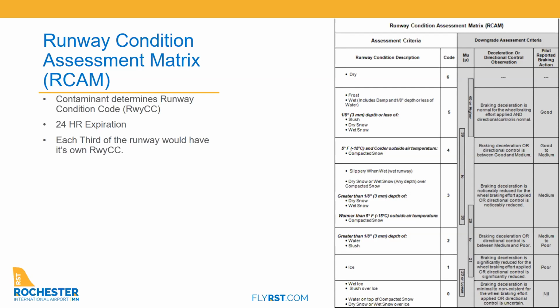But we always struggled with the fact that if I got a 1/4 inch of snow or I got 3 feet of snow, I'm getting a 3. And that's still the truth. But as Eric pointed out, if there's 3 feet of snow, or even realistically 6 inches of snow, that's going to increase his takeoff and landing distance significantly. So while we see a 3, he sees a 3 and a 6, and 6 inches of snow or 1/4 inch of snow is a big difference.